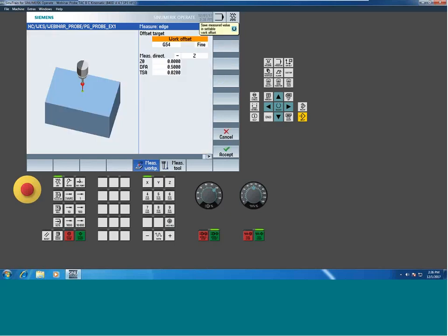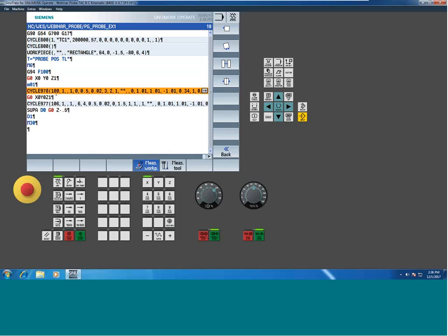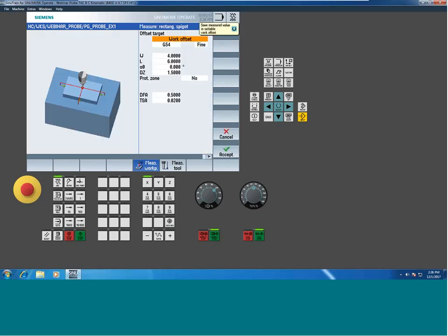Now I adjusted this one just a little bit, but here we're measuring in the work coordinate, G54, and we're writing to the fine offset. So we're doing that for both the Z measurement, and then when we walk around the boss, same dimension we just talked about. Now, if you want to see what the protection zone looks like, this would be a case where I could then give it some safety areas. I'm not too worried in my case. And then we can write that again. And again, you notice I'm writing to the fine as opposed to the coarse field.